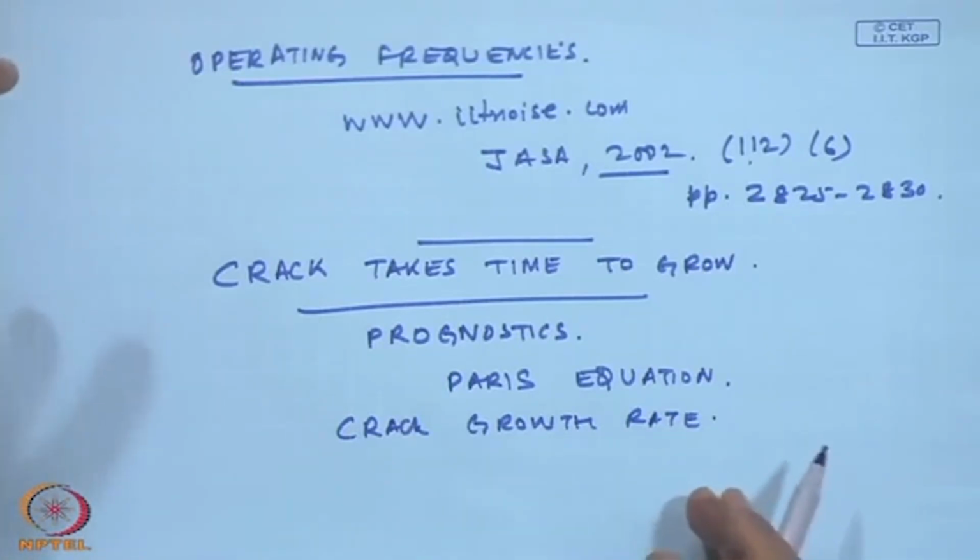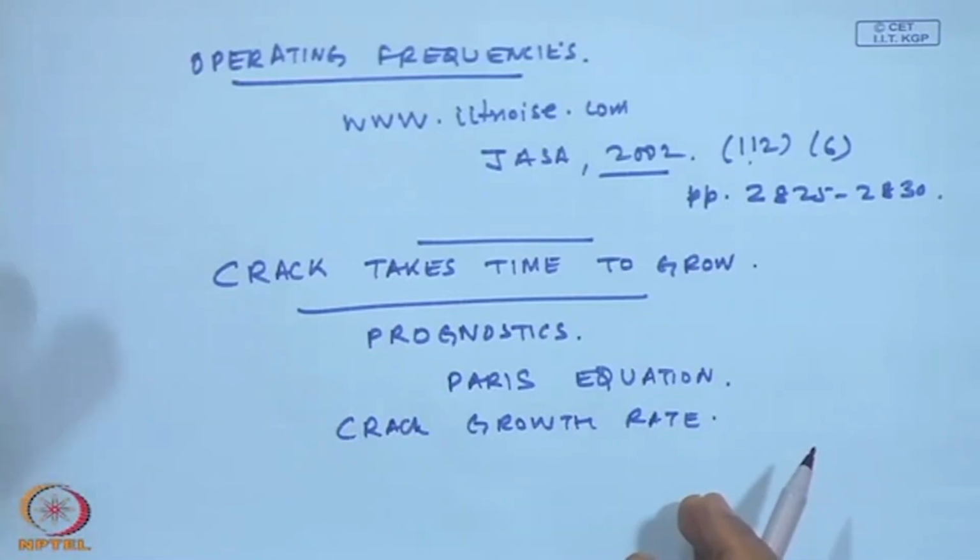But through a mobility measurement, when the crack has just grown to a few A's, 0.5, where A I define as the crack depth by D, we will see that the mobility value suddenly shoots up. So, mobility is sensitive to crack, unlike just monitoring the velocity of vibration. By velocity of vibration, it would be very difficult for us to monitor whether the crack has occurred, but by doing the mobility measurements, we can surely say the crack has occurred.